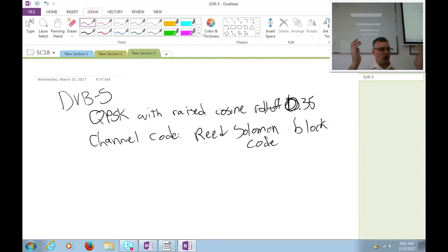a sort of free-running method of coding. It's very easy to implement in hardware. Ultimately, it has the same performance limitations that a block code has. You need more complicated convolutional coders to be able to achieve closer and closer to the Shannon channel capacity theorem.